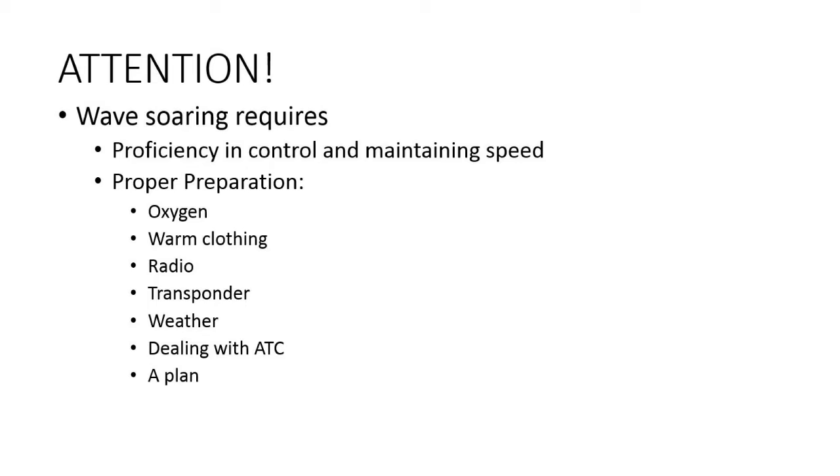Proper training, equipment, and preparation are required, including oxygen, warm clothing, it can get very cold, radio, transponder or ADS-B, weather planning, dealing with ATC including pre-approval for entry into Class A airspace, and a plan.